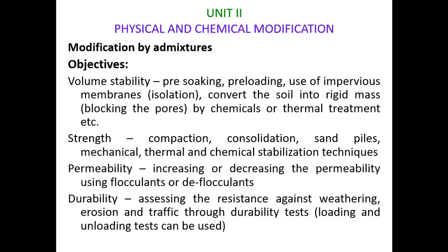Seasonal and long-term moisture changes in an expansive clay soil, if uncontrolled, disrupt road surfaces, crack buildings, break underground pipes and cause great economic loss. The solutions to the volume change are based on converting the soil into a rigid mass or retarding the moisture movement within the soil. The methods to control volume change are pre-soaking, pre-loading, use of impervious membranes, chemical and thermal